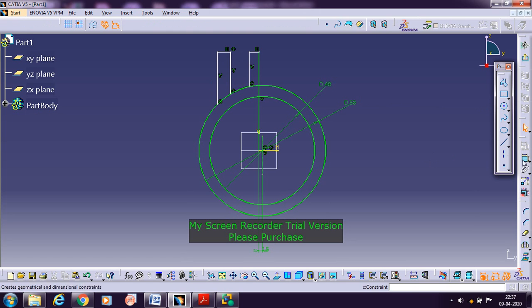Now we need to set the dimensions here. Go with the constraints. Here it is the vertical height from the central axis. Then this thickness is given, and then the individual thickness is given, and then the total measurement is given here. In this way we got the constraint condition. All the lines have changed to green color. Now we'll set it one by one.